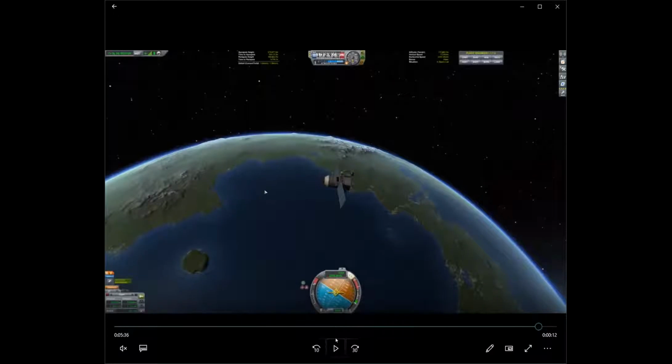Now, in a low Earth orbit configuration, satellites do hit the atmosphere because there's no set boundary between the atmosphere and space. For example, recently we, of course, had to deal with the Chinese rocket that was going to land somewhere, anywhere. We didn't know where. And why was that? Well, that's because the sun hits the planet, and that causes the atmosphere to expand in unpredictable ways. So if you're in a low Earth orbit, you will eventually decay from the atmosphere expanding, and you get little whiffs of air slowing you down.